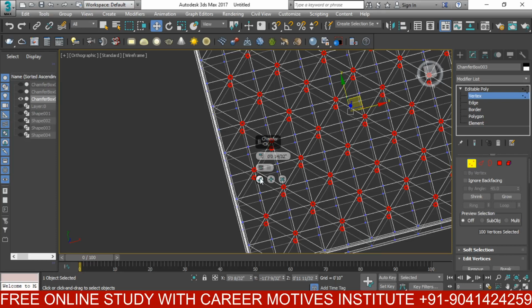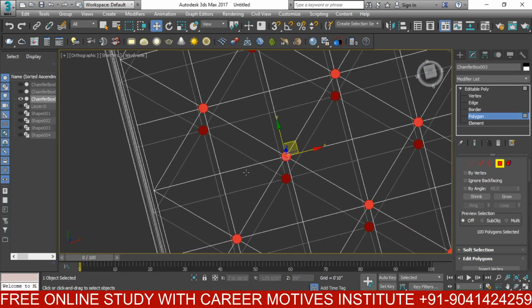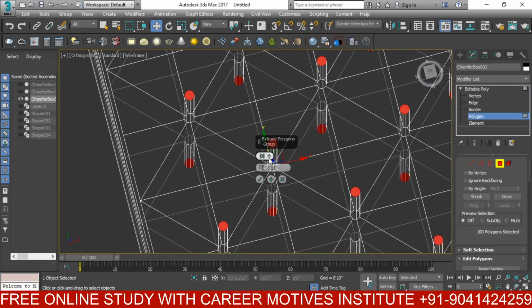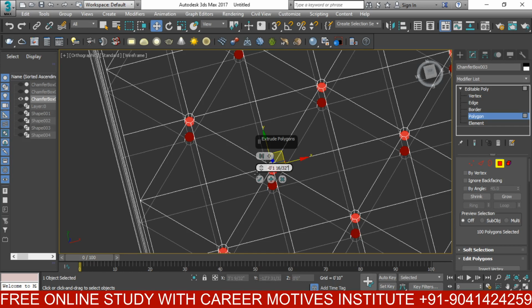Okay, then yes, then shift and alt together, shift and control, then polygon. Okay, right click extrude. Okay, and I'm taking extrude value minus 1.5 inch, then yes,